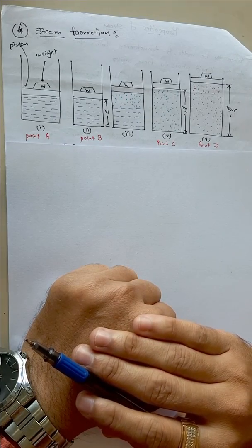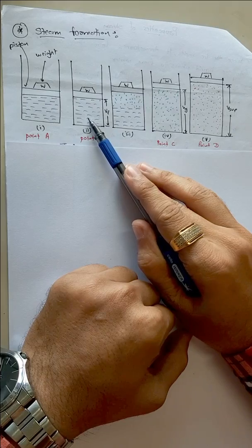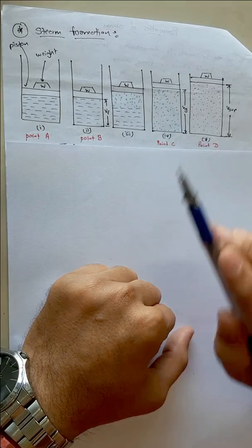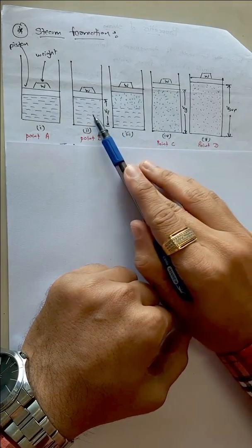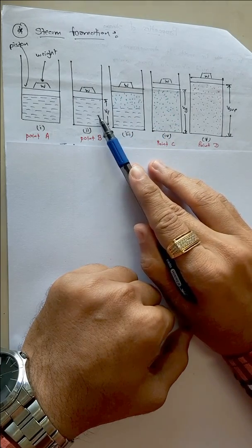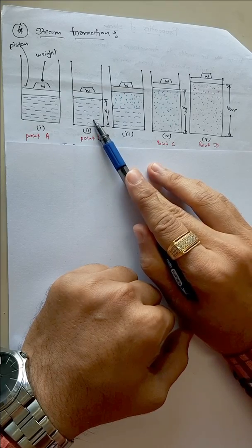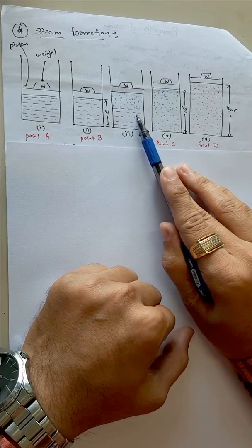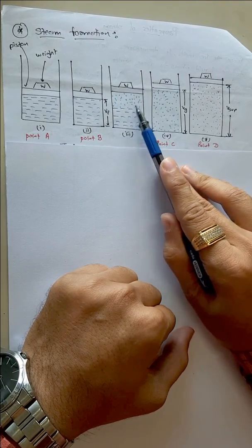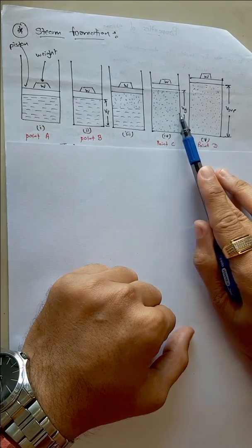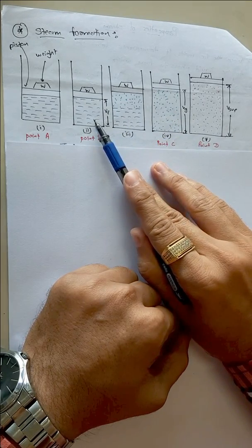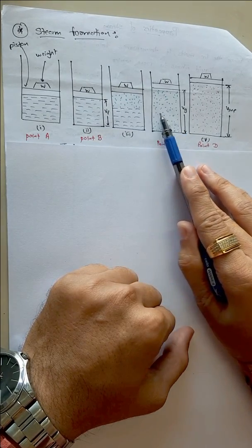One thing to observe is that from the saturated liquid state to dry saturated steam, the temperature of the system remains constant, that is, the saturation temperature. In figure number 2 we have water at 100 degrees Celsius. In figure number 3 we have a two-phase mixture of water and steam at 100 degrees Celsius, and at point C we have dry saturated steam at 100 degrees Celsius. So in figures 2, 3 and 4 we have the same temperature.